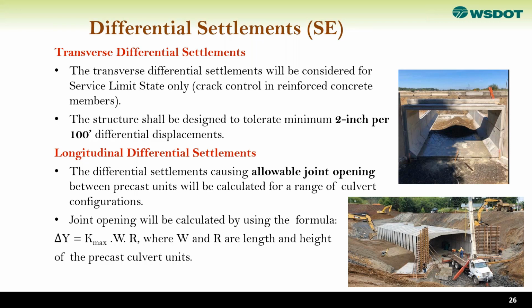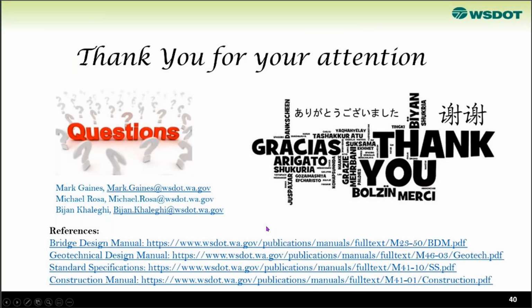Between the precast segments, the joints are designed for whatever the imposed shear is across those joints. Shiplap joints have been used before. We prefer more of a shear key approach, or in the past we've used grouted keyways, just to provide a two-way shear connection between precast segments for both longitudinal and vertical joints.